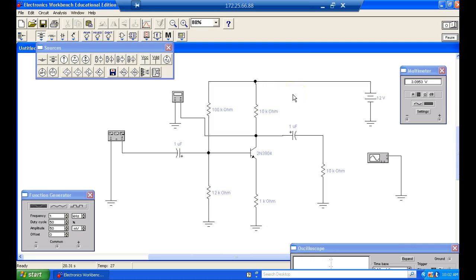Now, what could cause this to happen? Well, we could have a problem on the left-hand side, but that's really easy to check. I come over here and take my meter, and I move this guy right here over to there, right? And it measures exactly what it's supposed to measure, because the transistor's still conducting, we still see this as times beta, right? I come over here, and this guy right here is a lot lower than what's supposed to be. Which means what? The 10K is dropping more voltage.